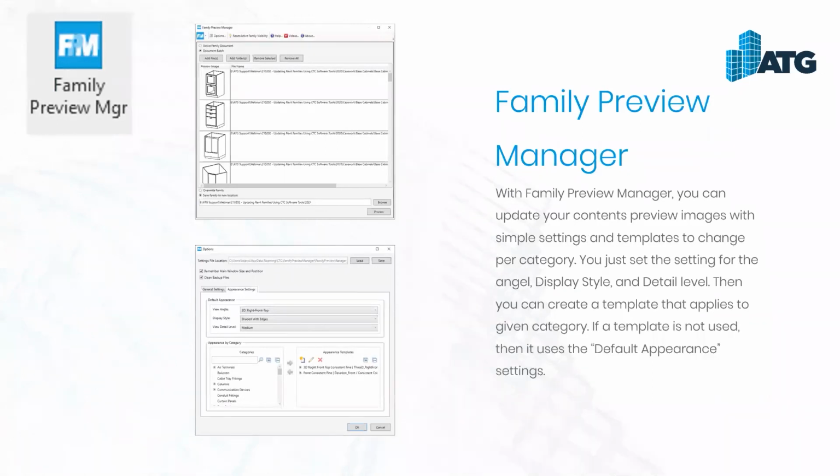And then the last tool I wanted to discuss on this particular topic, updating the family, is one of the newer tools in the suite. It's been out for a while now, but it's one of the fairly newer tools: Family Preview Manager. This tool is designed to go through your content and update the preview image. The nice thing about it is you have the ability to specify what you want to do with certain categories.